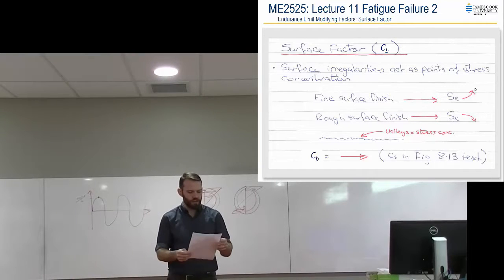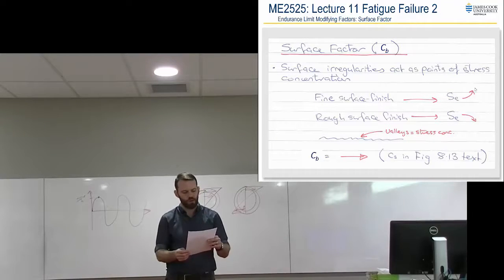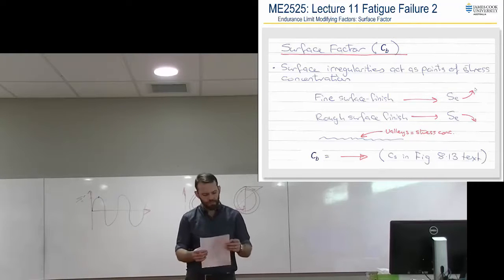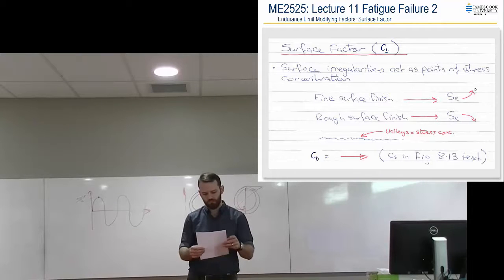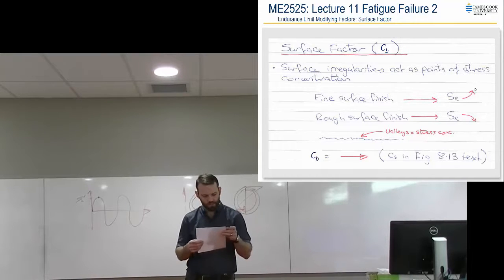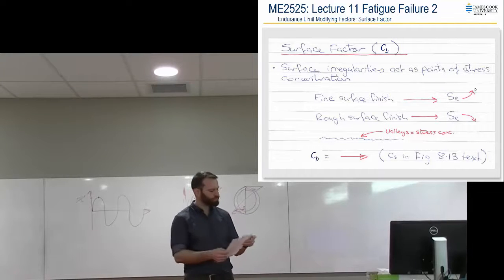Alright, and you can see that along the horizontal axis we've got tensile strength. The first one is in KSI if you have it in KSI. The one below it is in GPa if it's in SI units. But it's all the same. So 400 megapascals is our left-hand end, and 1.8 gigapascals is the right. And so you just choose your tensile strength, and then you move up to that line, and that line's 0.9 until you get very, very, very strong steel.